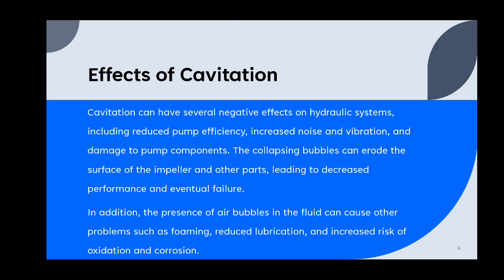These collapsing bubbles can erode the surface of the impeller and other parts, leading to decreased performance and eventual failure. In addition, the presence of air bubbles in the fluid can cause other problems such as foaming, reduced lubrication, and increased risk of oxidation and corrosion.